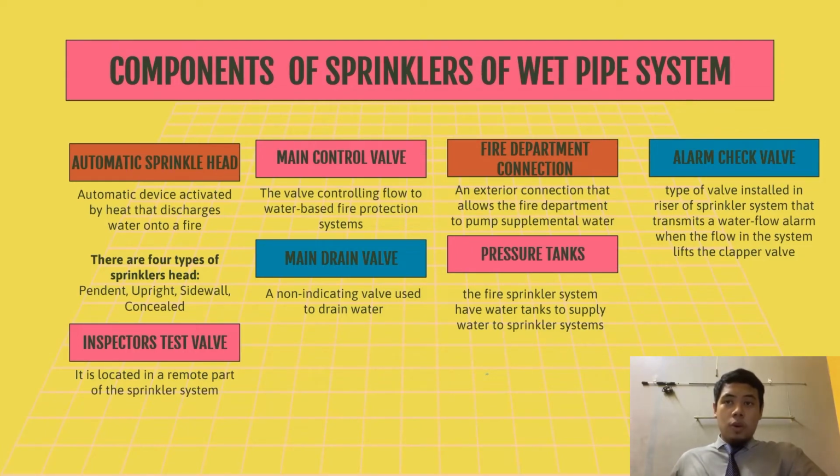The sprinkler operates automatically when the air temperature rises to or above the device specified temperature ratings. There are 4 types of fire sprinkler head. Example like pendant, upright, sidewall, and conceal. And we have identified the fire sprinkler head for this figure is pendant. A pendant fire sprinkler hangs from above ceilings pipe and distributes water in a dome or conical pattern using a convex deflector.